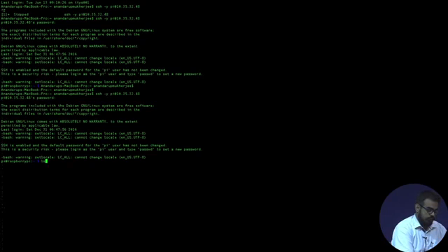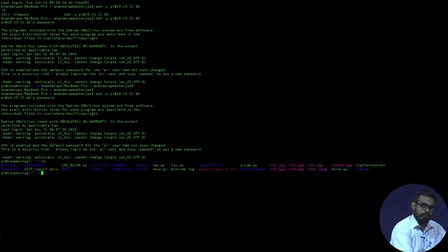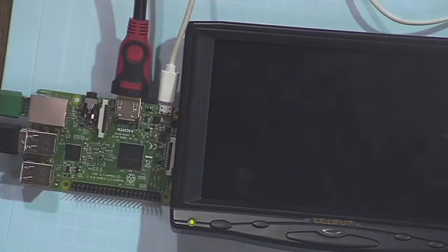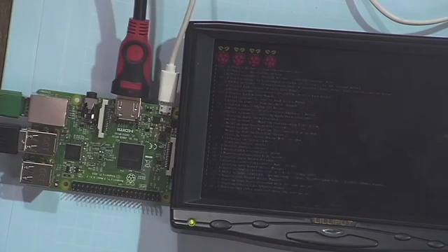So you can just see your file system, what exactly is there. You can give a basic ls command to list files. So these are some of the directories or files within your Raspberry Pi. You can even remotely restart your Raspberry Pi. So for the end of this lecture, I'll just reboot my Raspberry Pi. So I write sudo reboot, press enter. As you can see over the monitor, my Raspberry Pi has gone into reboot. Again it is starting up.